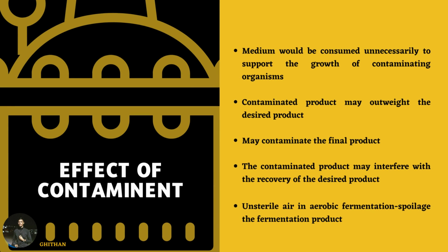Now, I would like to explain the effects of contaminants. Medium would be consumed unnecessarily to support the growth of contaminating organisms. Contaminating organisms may outweigh the desired product, and may contaminate the final product. The contaminated product may interfere with the recovery of the desired product. Unsterile air in aerobic fermentation can spoil the fermentation product.